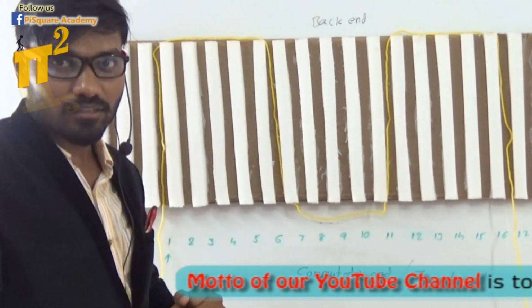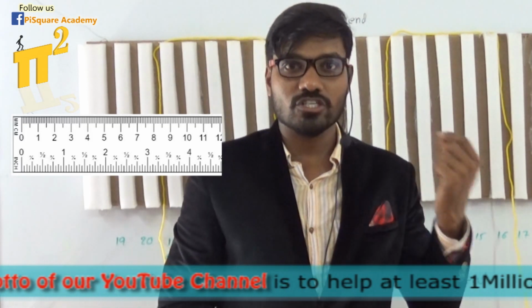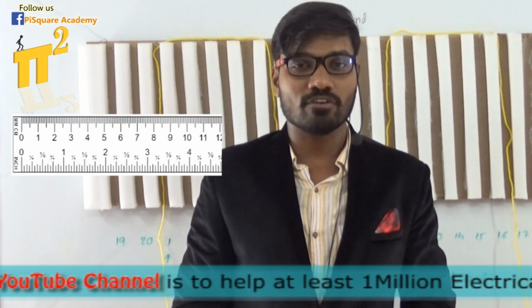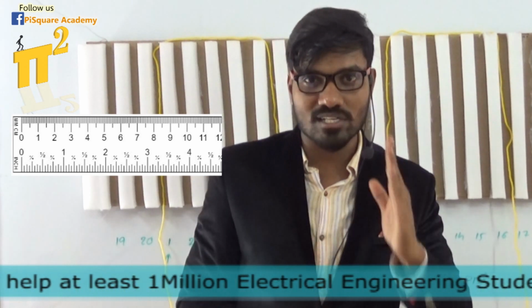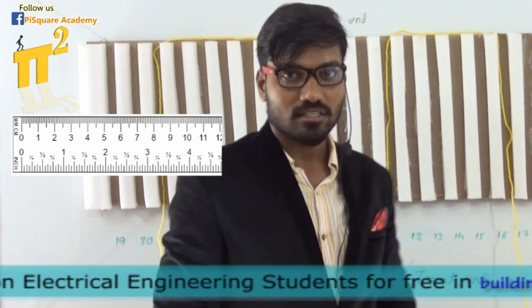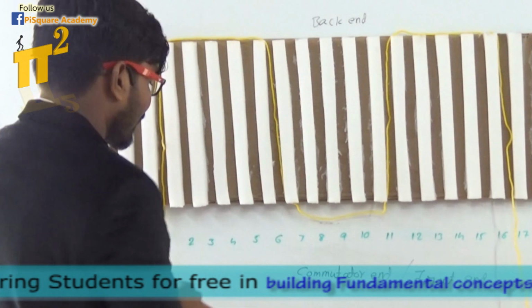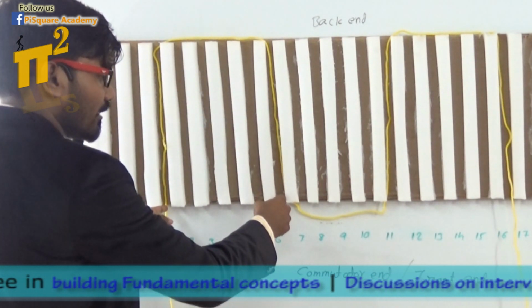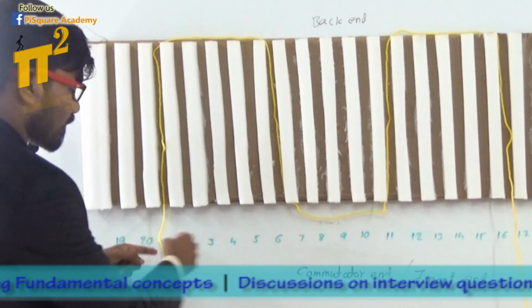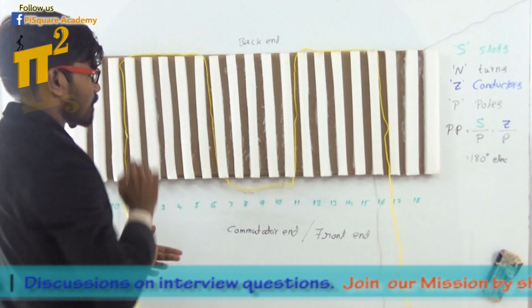That's wrong. Because if somebody is asking you what is the distance between 0 centimeters and 5 centimeters, what would you say? The distance is 5 centimeters. If somebody is asking what is the distance between 1 centimeter and 5 centimeters, then the answer is 4 centimeters. So here, you should use the same terminology. Distance between 6th slot and 1st slot. How much is that in terms of slots? 5 slots. 6 minus 1 simply. Alright. So that is coil span.